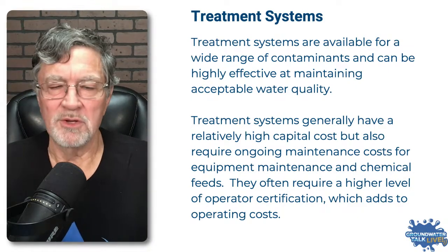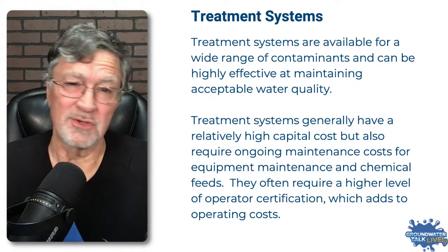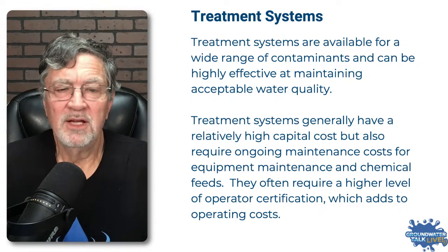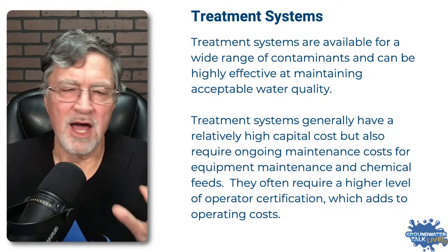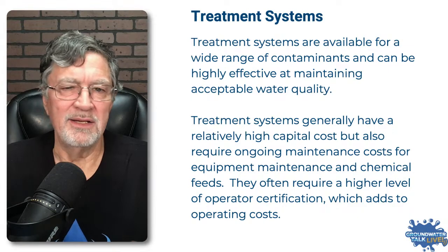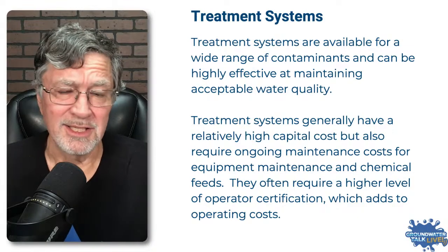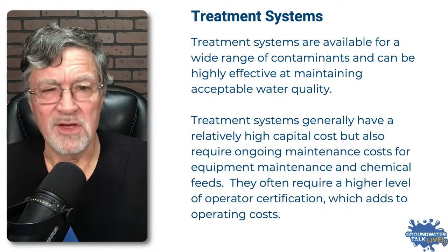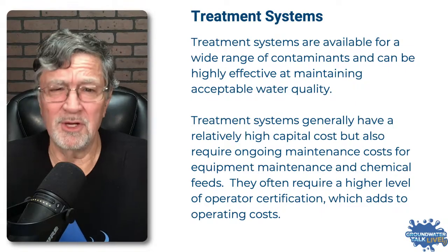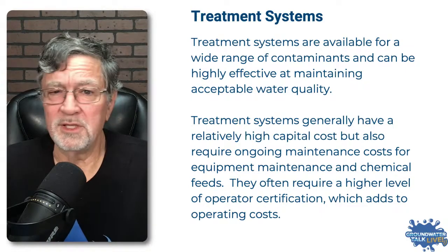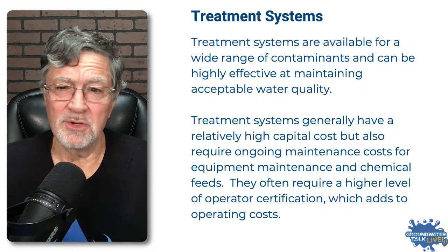If you're using a reverse osmosis system, what are you doing with the brine? How do you treat that? There's costs involved in that. For an ion exchange system, for instance, you got to change out the ion exchange resins and deal with that. Going back to the reverse osmosis, you got to clean that screen, flush it, and then you got to deal with the brine. So it can be expensive. Other things require some back flushing, dealing with the wastewater. So you got to pump it to waste and deal with that. So a lot of maintenance goes into that.